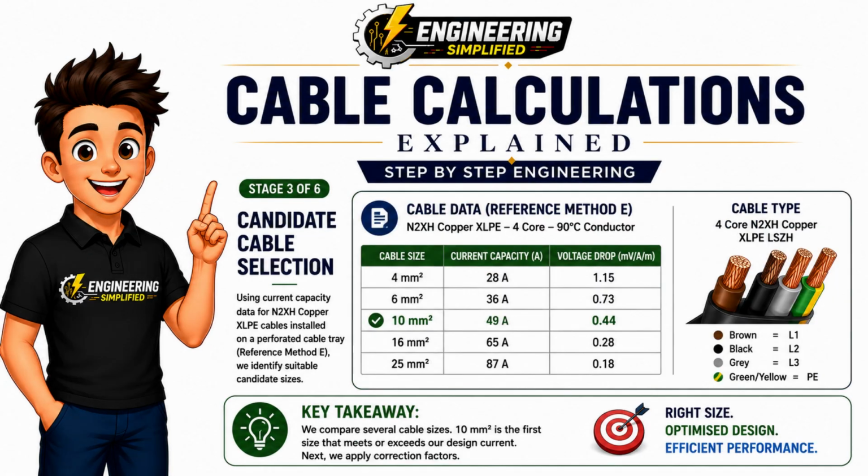With the design current known, we can begin selecting a suitable cable. Using the manufacturer's cable data for N2XH copper XLPE cables installed using reference method E, we compare the available cable sizes against our required current of 37.1 amps. The first cable capable of carrying this current is a 10 square millimeter cable with a current rating of 49 amps. At first glance, this appears to be a suitable choice. However, we're not finished yet. In the next section, we'll apply the correction factors to see whether this cable is still suitable under the actual